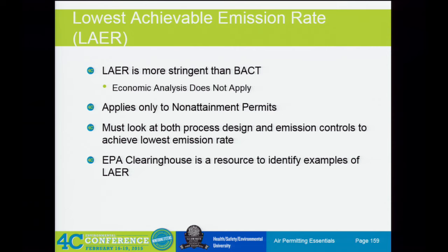If nobody's demonstrated that, but only in a lab, as long as you can confirm that it cannot be met on an industrial level, that should be sufficient. But like I said earlier, a lot of non-attainment permits go into contested case hearings, and they'll contest your LAER determinations and try to come up with off-the-wall ways to decrease your emissions and argue that that's LAER versus what you decided to be LAER.